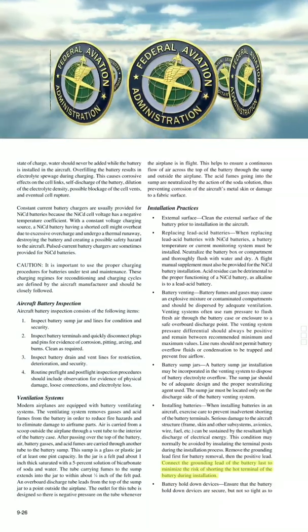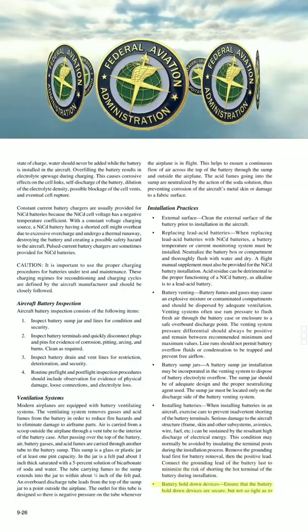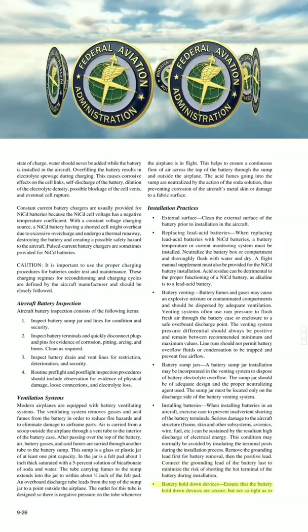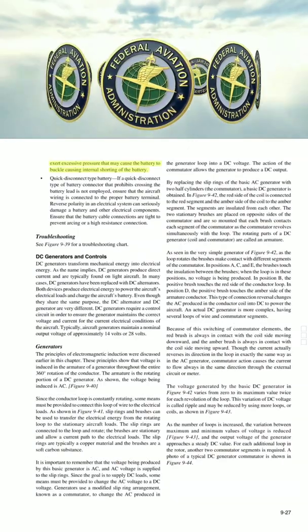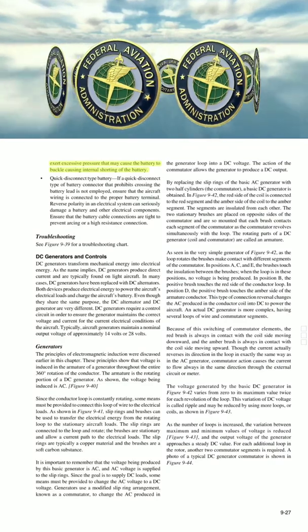Battery hold-down devices. Ensure that the battery hold-down devices are secure, but not so tight as to exert excessive pressure that may cause the battery to buckle, causing internal shorting of the battery.